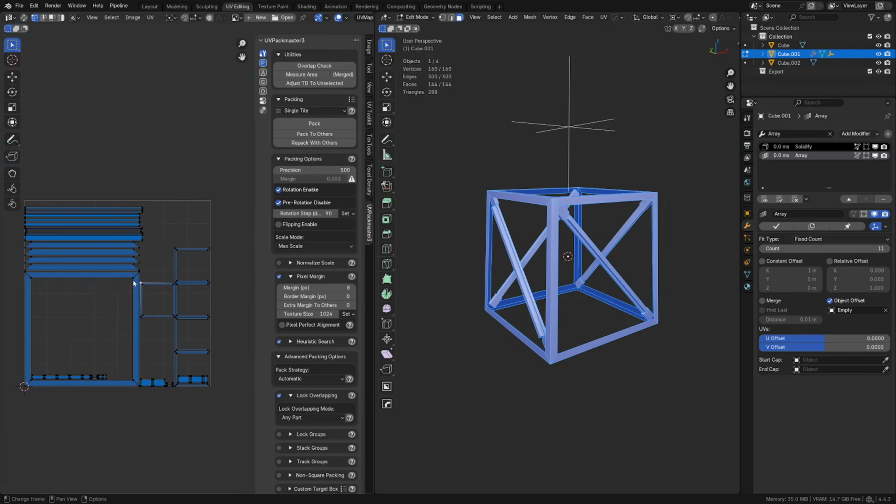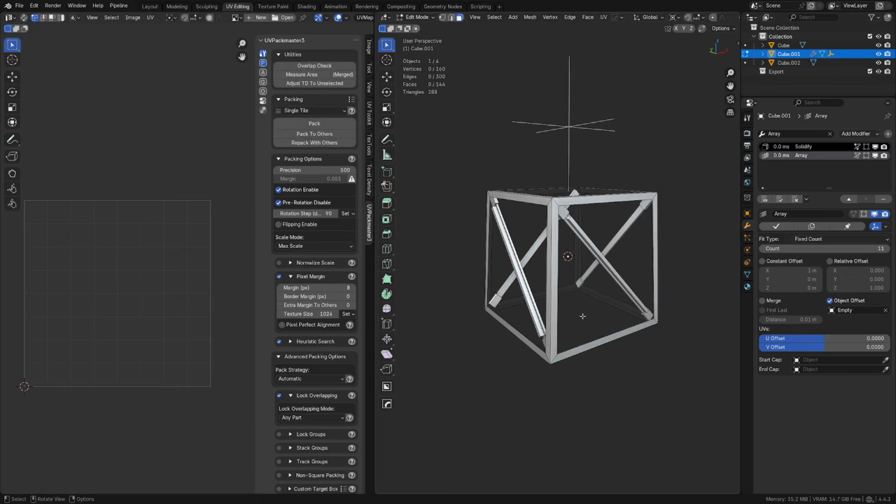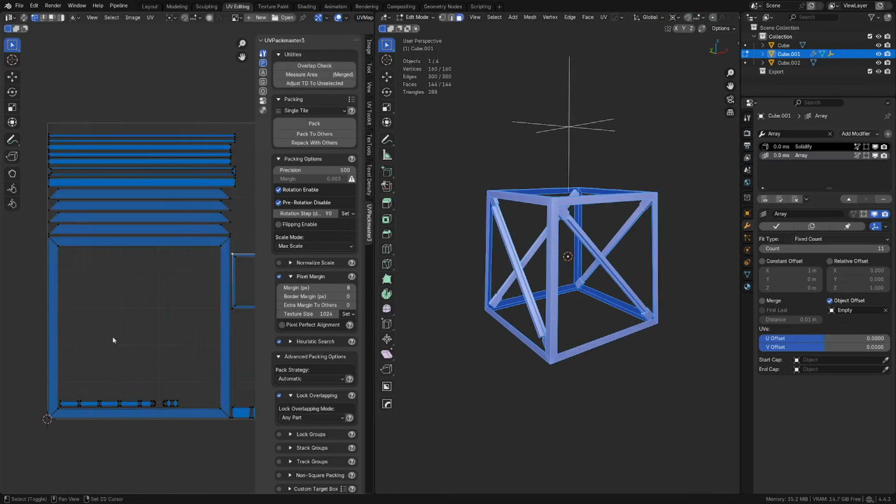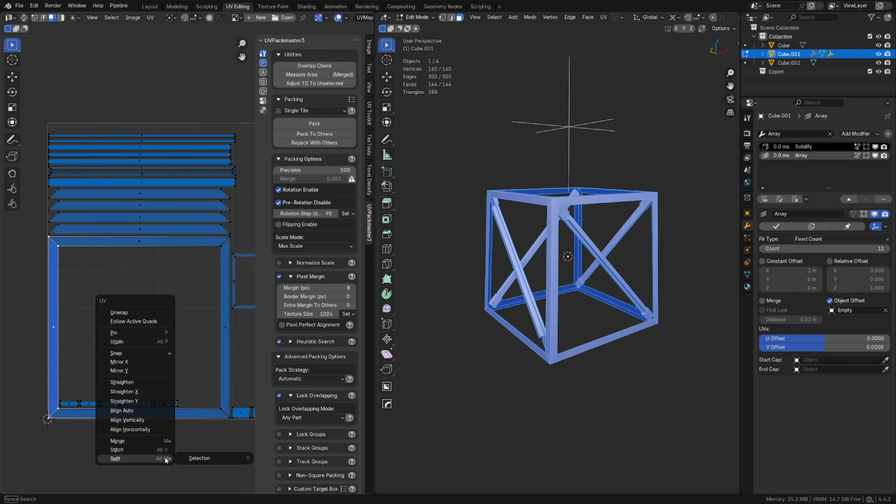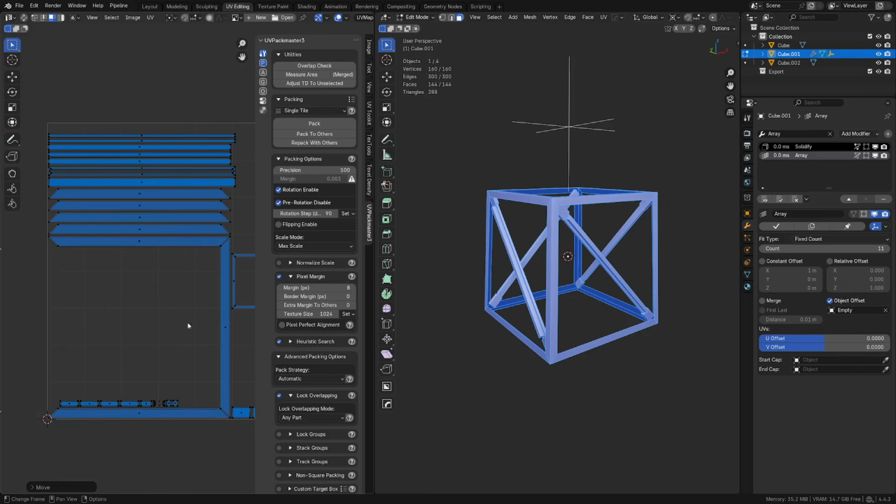These would be better if we broke apart as well so that they don't eat up so much space. And this whole island would look way better if we had done that. Now, how do we actually do that? There's different ways. Maybe we grab the face right here and you can hit Y and it should rip it. I don't know why the menu's like this, but Y here. So just Y rips, boom. Y rips, and then boom.